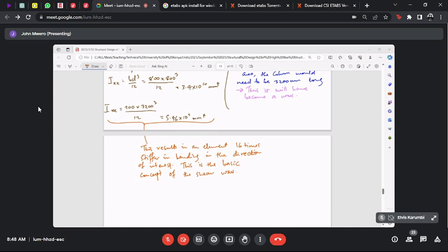So when we get there, maybe just for your interest, you could do a U-shaped building or an L-shaped building or a circular building with a hollow core, and put in the loads once we have discussed how to put those in, and run this model and see how it responds dynamically, and run this other hypothetical building, and do that. Generally, it is preferred to just make the building form as simple as possible for earthquakes.